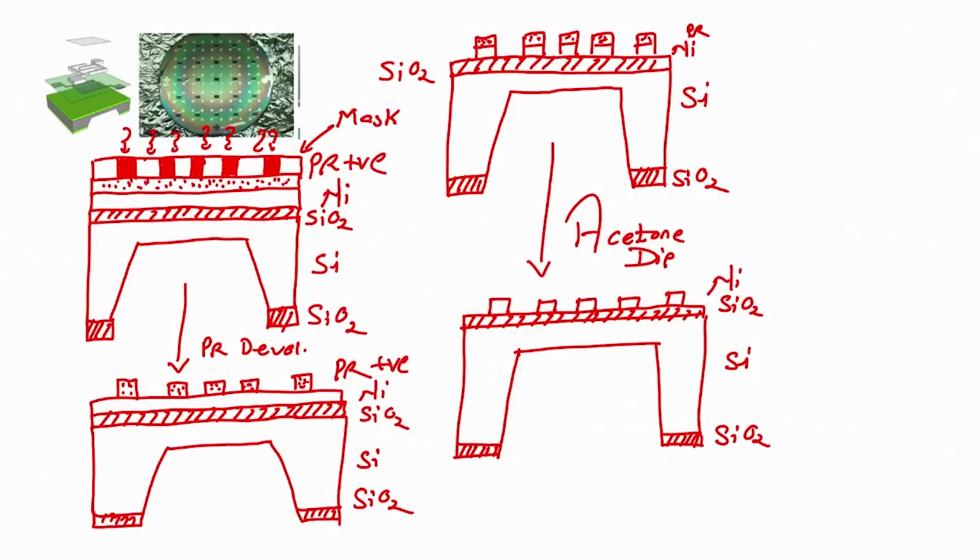Next step would be to form interdigitated electrodes. Now, nickel is the material for the heater, right, but nickel is also a metal. So, now if I want to fabricate interdigitated electrodes on the heater, I cannot do it, right, because it will be shorted, we cannot have metal and metal. So, what can we have? We can have an insulating layer between two metals. So, if you come back to the screen, the next step would be to grow silicon dioxide.